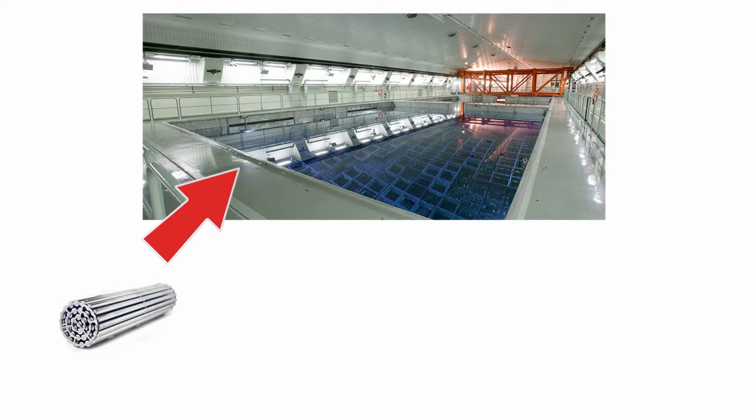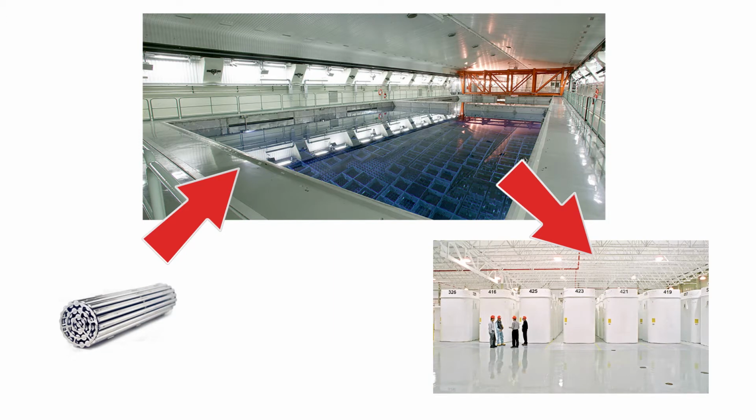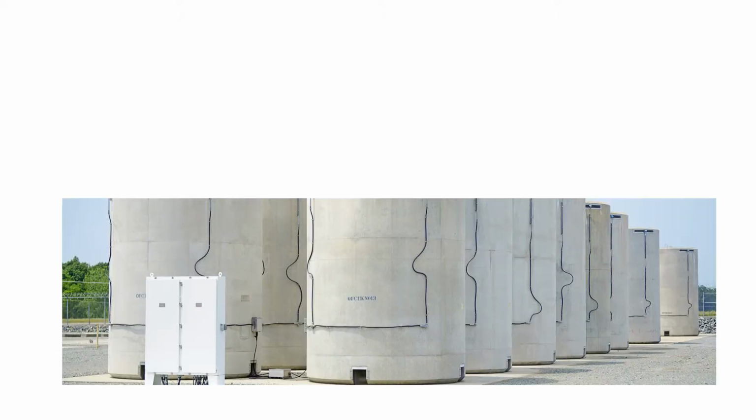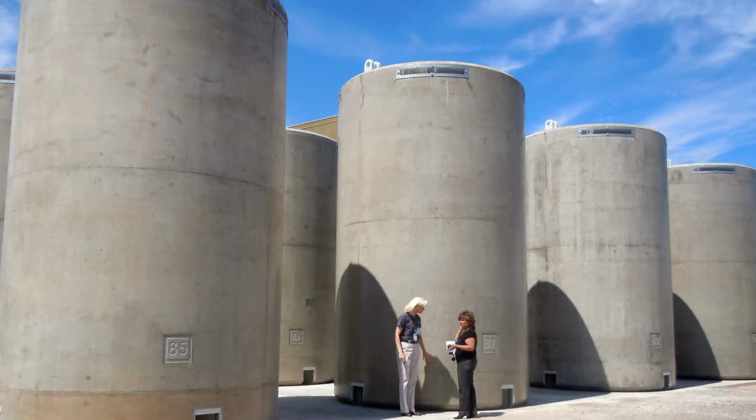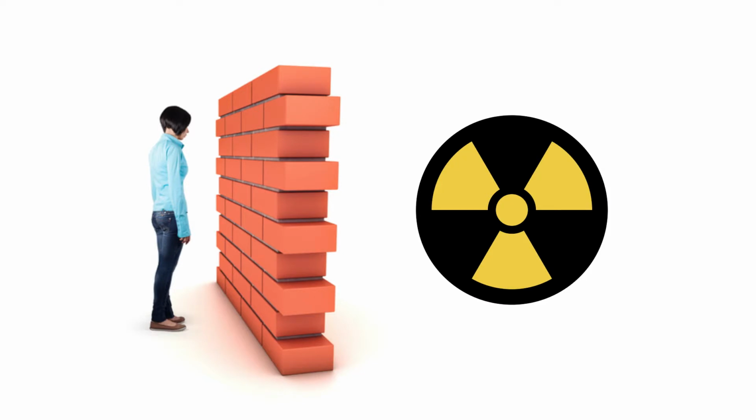Spent nuclear fuel bundles are transferred from a reactor to a water-filled pool where their heat and radioactivity decline. After 7 to 10 years, the bundles are transferred to dry storage containers. Dry storage is a well-known technology that has been tested and verified in the industry since the 1980s. Dry storage containers are made of reinforced high-density concrete that are lined inside and outside with half-inch steel plate. The thickness of the concrete and steel provides an effective barrier against radiation.